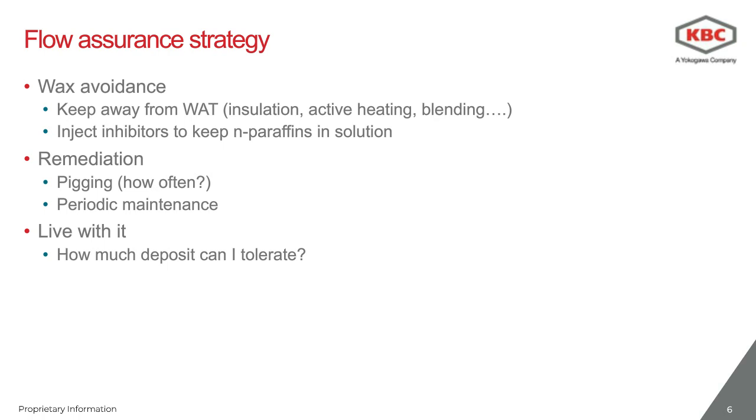In extreme cases, one could inject some wax inhibitors to keep the N-paraffins in solution, although that's not as common as with hydrates remediation. In cases where the temperature is going to drop below the wax appearance temperature, and we know that deposit is going to form, pigging is obviously the most common method for remediation.